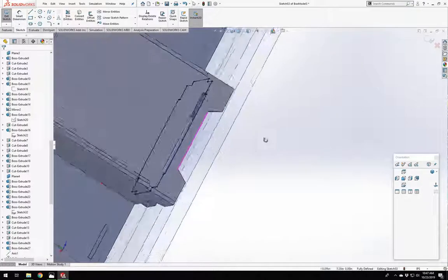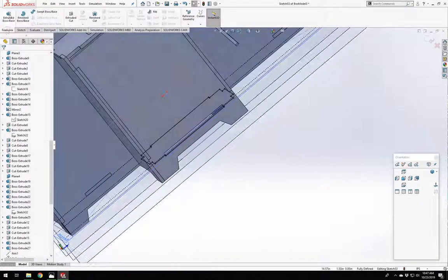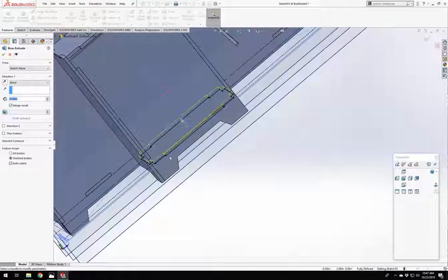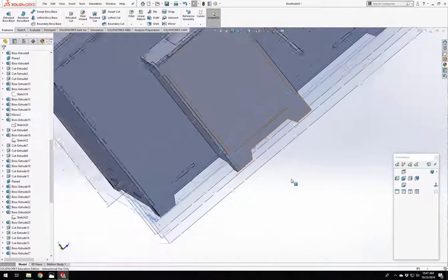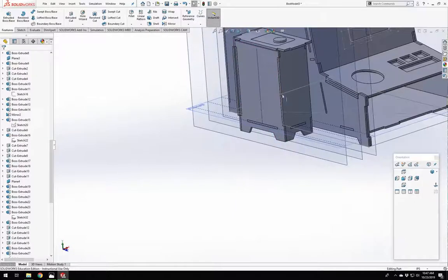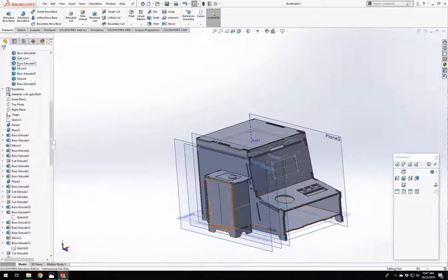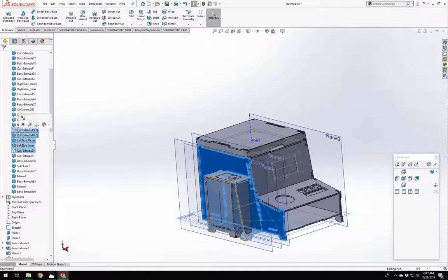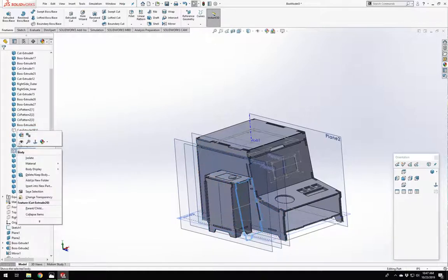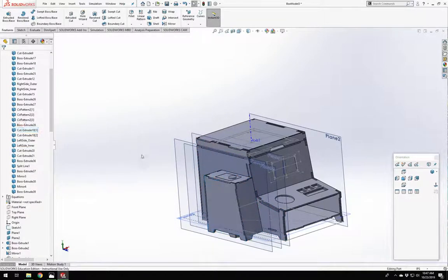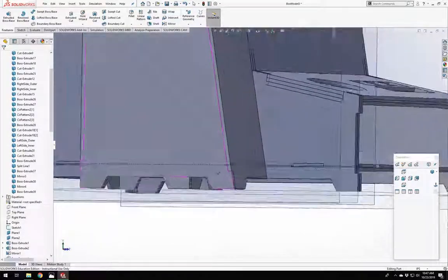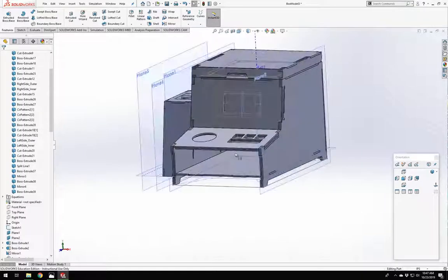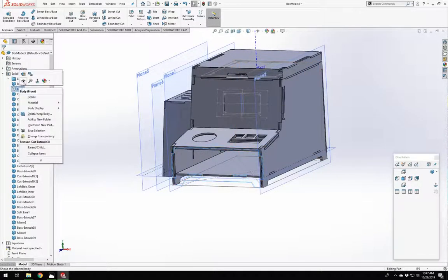All right, cool. So we've got our base there. We can extrude this guy, and we'll just do it as sort of a relative up to that vertex, we don't want to merge. There we go. So we now have a box to catch whatever gets poured into there. Let's bring back some parts here. And not only do we have that, the box looks pretty good. Kind of makes sense under there. All right, we're going to bring back the front.